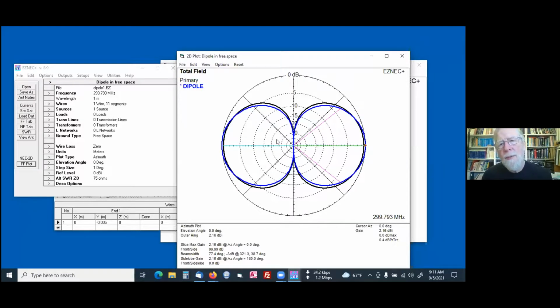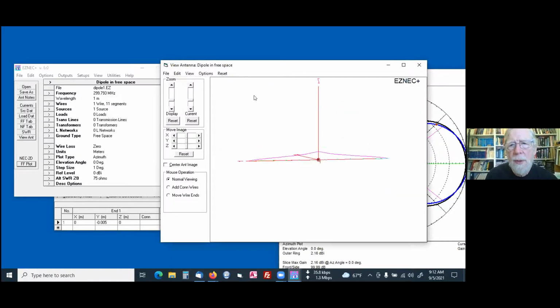So the fact that a short antenna does not, in real life, in your experience, radiate as effectively as a long antenna isn't something to do with its ability to radiate. By the way, the reason that the patterns are different at all is the current distribution on the antenna. The current distribution on a half wavelength antenna is pretty sinusoidal. It looks like a sine wave, and this antenna is more linear.